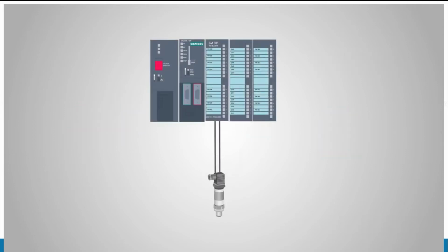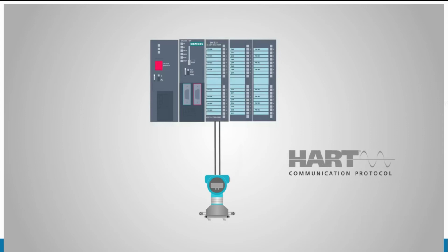And because HART-enabled sensors require only a single pair of wires for communication, to upgrade an existing non-HART sensor loop to a HART-enabled loop, no wiring changes are required. Of course, both the sensor and the analog input card at the controller would need to support HART. The good news is that HART is built into most commercially available analog sensors, and HART-enabled analog input cards are available from nearly all DCS and PLC manufacturers. There are even add-on hardware devices to convert your HART sensors into wireless transmitters.